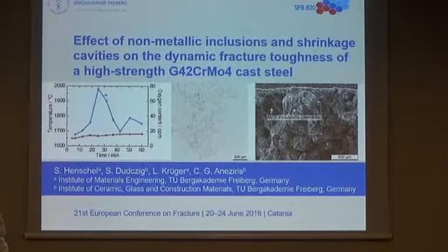We had only slight effects of the location within the cylinder on the strength, so it's quite homogeneous. But we observed the highest deformability at the top of the cylinder, because shrinkage cavities were mostly observed at the bottom of the cylinder. These were only relatively small shrinkage cavities. And as I told, the dendritic MnS, or manganese sulfide inclusions, pronounced of course the damaging effect, as they act mostly like a crack.